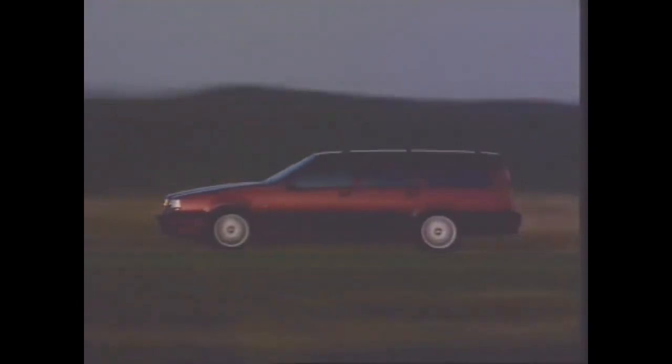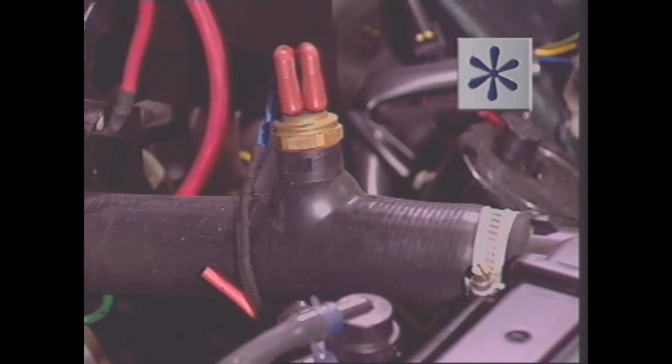At high speeds, plenty of air is already flowing through the radiator. If the fan is always working at full speed, it's a waste of energy. And since the engine drives the fan, it's a waste of fuel too. What's needed is some way to control the fan. A heat-sensitive switch in contact with the coolant can work like a thermostat and turn the fan on and off according to coolant temperature.